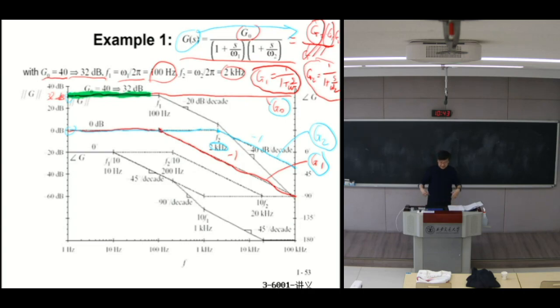These three things adding up together, always 32 dB, until it comes to the first pole frequency, which is 100 hertz. When this first pole occurs, the overall response changes, because these three adding up together is going to be G0, which does not change, still flat.